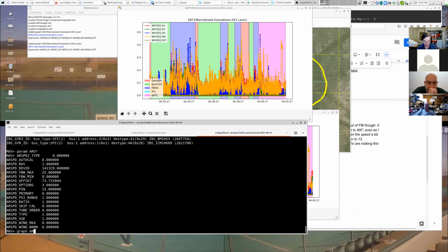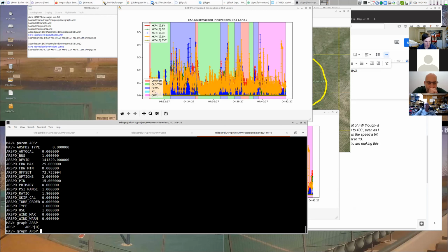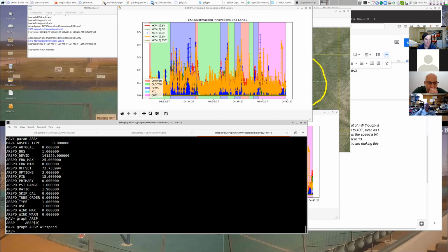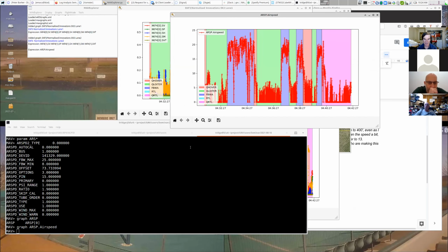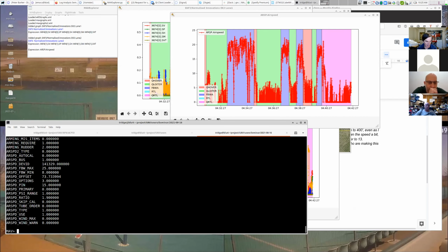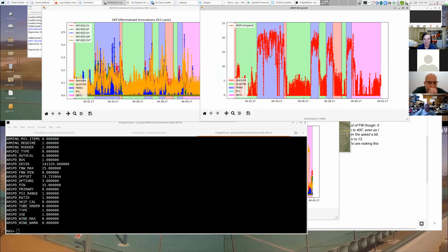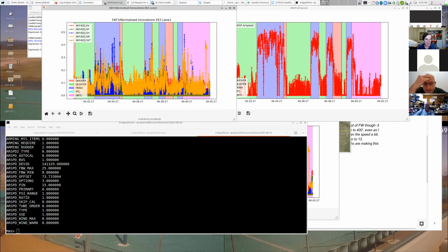It could be that it was flying the wrong speed. So, airspeed. Yes, he definitely had airspeed. Let's see what the airspeed fly-by-wire min and max are. Fly-by-wire min is 8, fly-by-wire max is 25. Yes. So that's actually a puzzle here. His airspeed is in range. It's in the range that we want, between the minimum and the maximum. And yet we're not seeing any true airspeed innovations.